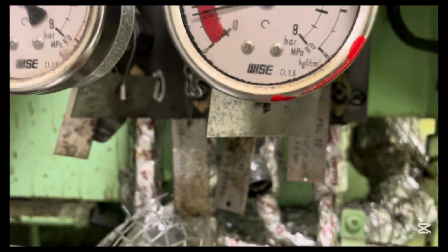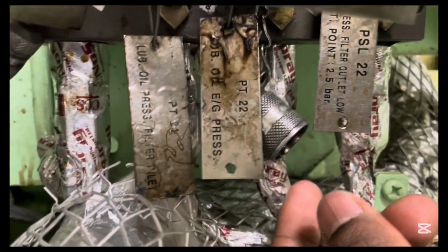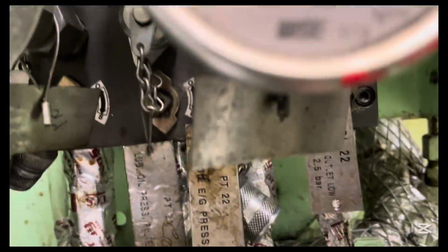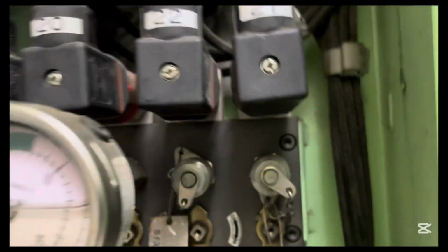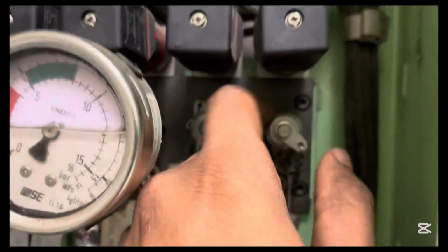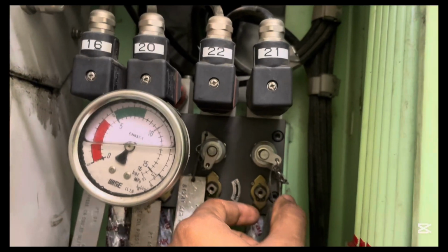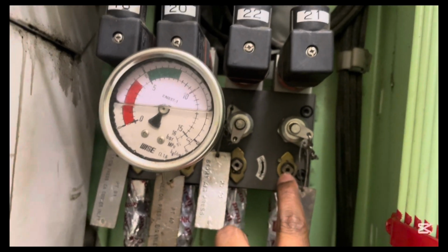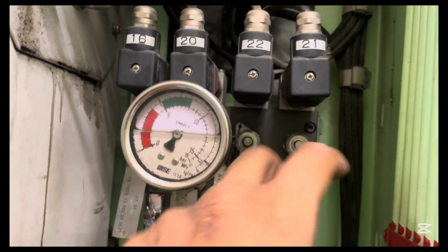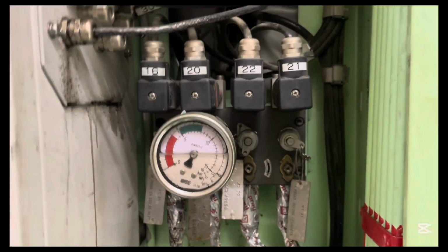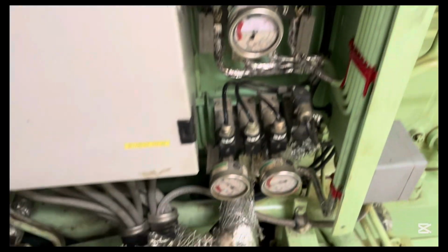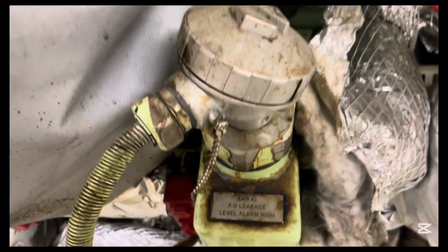with the sine wave. As we are seeing over here, there is also a test procedure for this. Either you can test this and simulate the alarms using, for temperature, maybe a temperature calibrator, and for a pressure transmitter, maybe a pressure calibrator. If not, you see a valve over there. This one you have to close to stop the flow, then release the pressure. Then you can activate the alarm. So this is how you activate an alarm from the pressure transmitters.